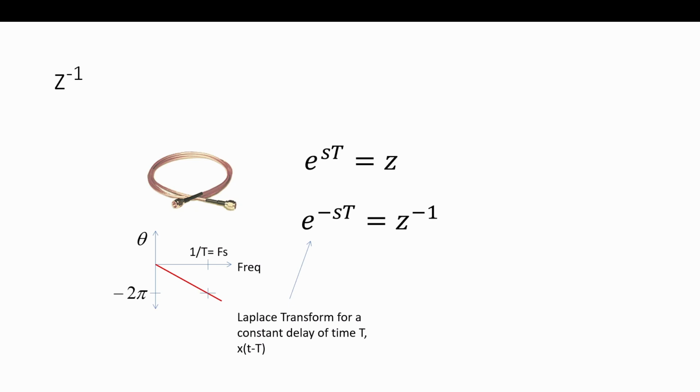The phase divided by 2 pi of the whole sine wave. It's going to be very small for the low frequency sine wave. And then as I keep increasing the frequency of the sine wave, if I compare the input to output for that same delay, there's going to be a lot more cycles potentially between input and output. You're going to see the phase gradually increase as I increase the frequency. Make sense?